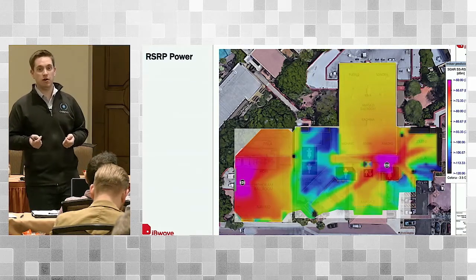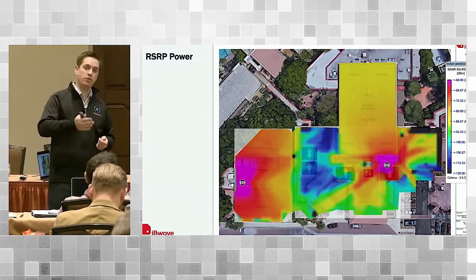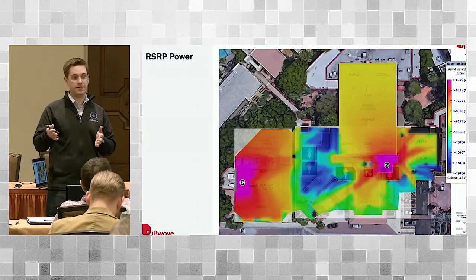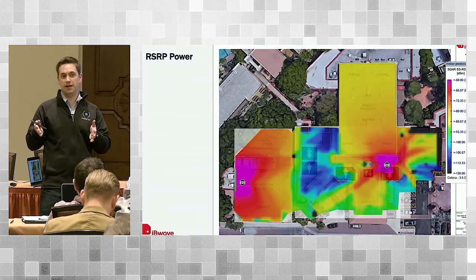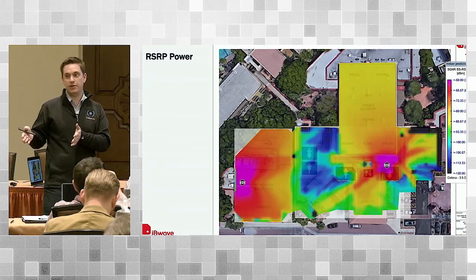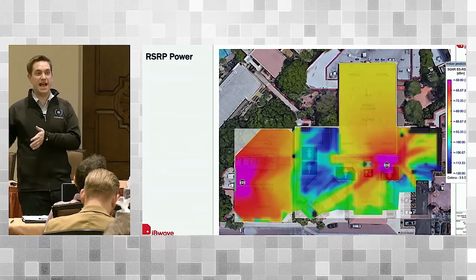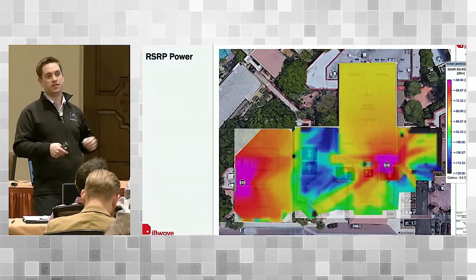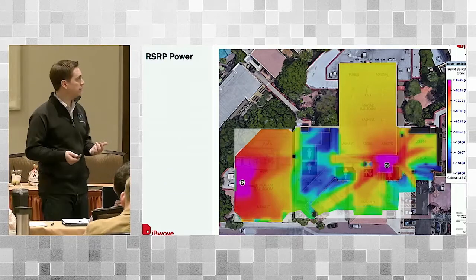Just like you think of RSSI today with Wi-Fi, even though RSSI used to mean, and by the standard means, a scale of 0 to 100, we use it as dBm in Wi-Fi today. That's what RSRP technically is. So technically, we're not using RSSI the way it was defined. We've adapted it to be analogous to what RSRP is in the cellular world. So it's just receive power.